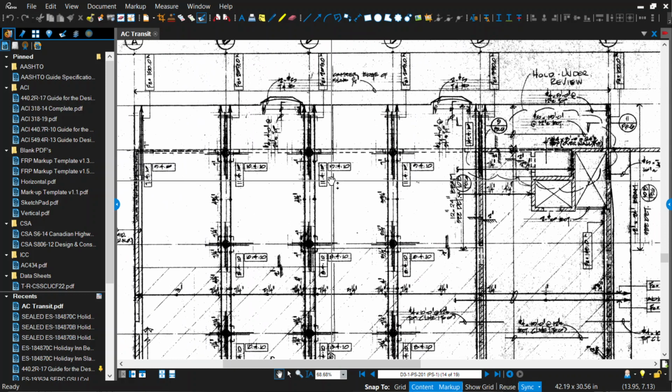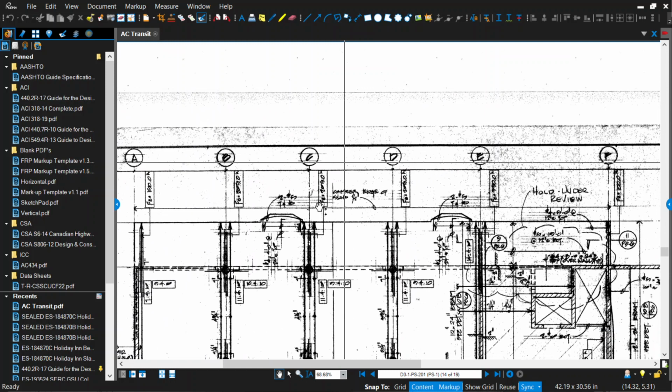It's hard to know when we're doing rebar equivalents whether or not an engineer has taken all that into account, or they're basically giving us the exact length where they need the additional force. So we should always, to be conservative, always plan on extending it past that. Okay. And if it has to be 12 inches for the first layer, then 6, 6, 6, then it is what it is. But when the engineer makes these drawings, they're including the actual length, right?